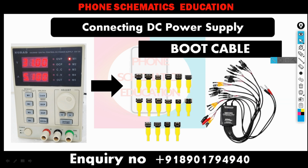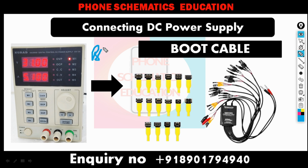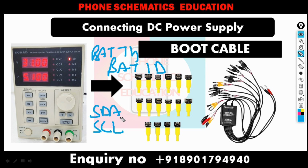Now in the market, you will see this type of boot cable with different connectors attached. Basically, it's a special cable designed for connecting the DC power supply to the phone motherboard. Because in modern phones, there are other pins in the battery connector called BAT thermal and BAT ID, right? In some phones, SDA and SCL. We're just talking about BAT ID and BAT thermal right now.